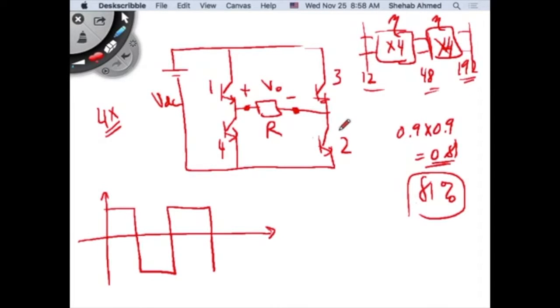Another way to do it is what you're doing in the project. What you're doing in the project, you have a full bridge inverter that you are creating a high frequency AC waveform from. This high frequency AC waveform, is it a nice, beautiful sine wave? No. And I don't care for it to be, because I'm going to rectify it afterwards, right? In your case, in the full bridge DC to DC converter, when you make a full bridge DC to DC converter that has a front end, basically, which is a high frequency DC to AC inverter, you don't care about the frequency content. But if you do the Fourier series for this, what will you find?